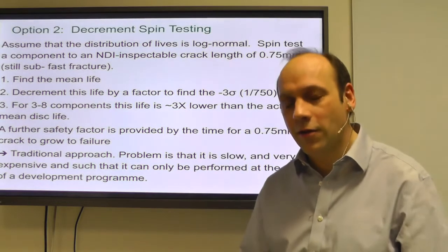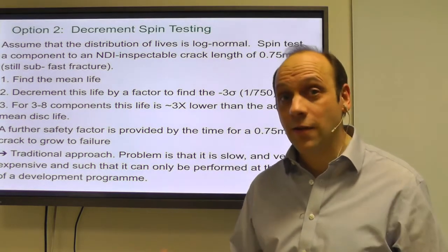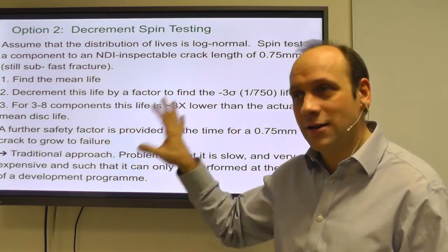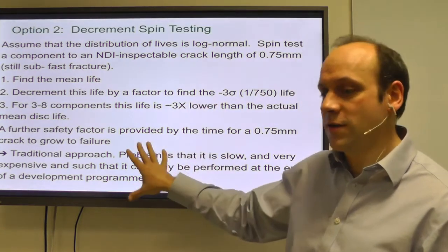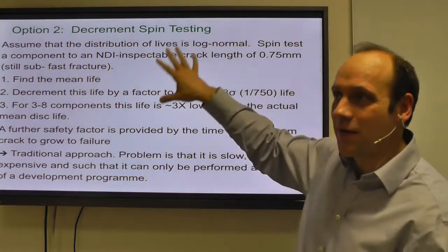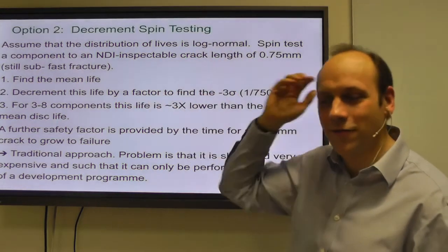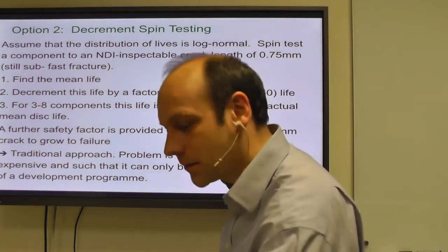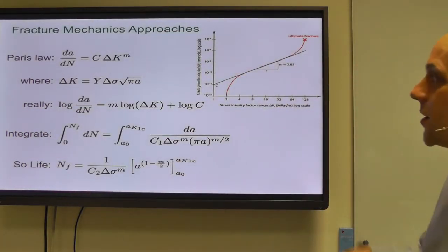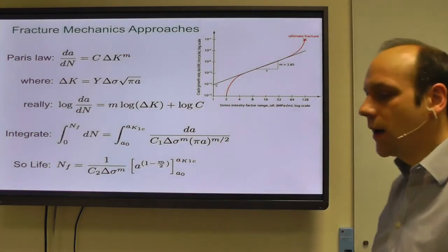And then you have to go through another 12-month design process at the end of your engine design sequence. So this is very expensive and slow and creates a lot of program risk. So you'd rather not do it. Actually, people do it, but they do it as a confirmation that they've done everything right up to that point. What people do in design is they want to do something more intelligent using fracture mechanics.